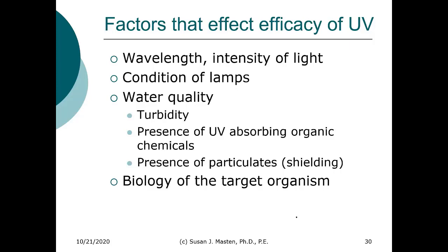So for instance, turbidity, anything that absorbs UV light would then prevent transmission. And also the presence of particulates can shield the bacteria from the UV light. And then again, the biology of the target organism plays a significant role.